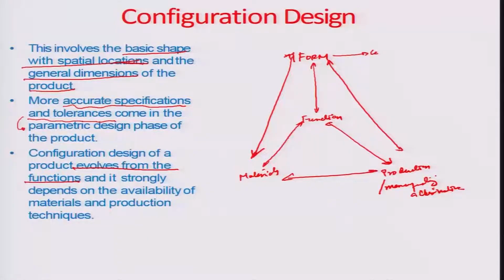So, obviously, the form has components. Okay. The form does have also interfaces between these components, and when we talk about particularly the next step, which is the parametric design process, these interfaces and the dimensions and tolerances along these interfaces become of immense significance in defining the product architecture. And of course, there are constraints like physical constraints related to motion, related to binding between different subsystems at the boundary or the interface.